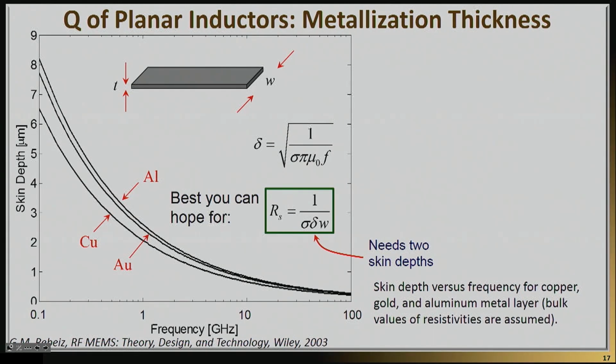So in the metallization, the first thing that we need to remember is that you're always limited by some type of T, the thickness of the metal that you can use, but you're also limited to the width of the inductor. Of course, it's always a good idea to make a very wide turn, but then the inductor gets huge, and again, that consumes too much area.